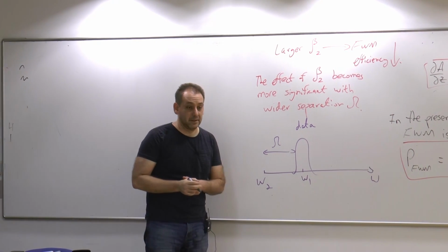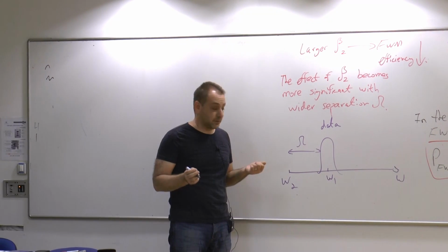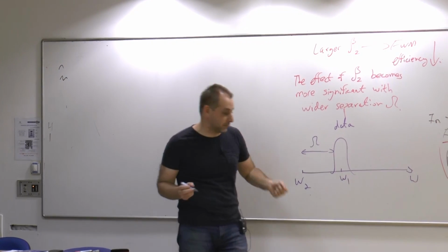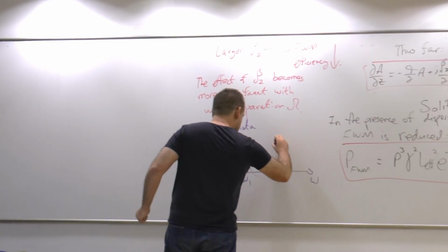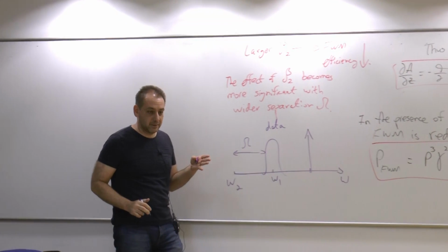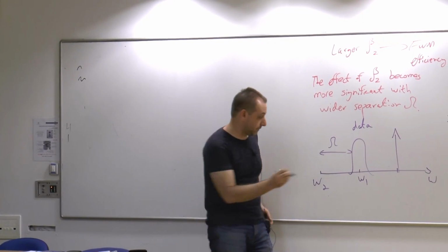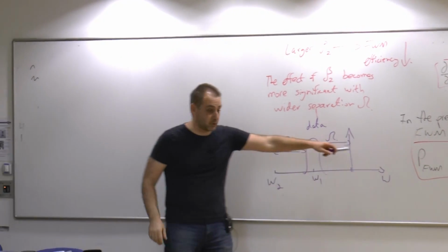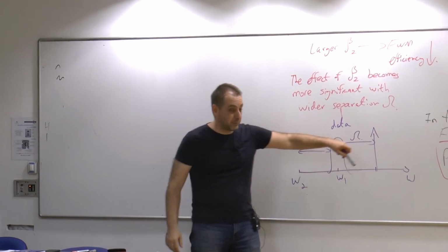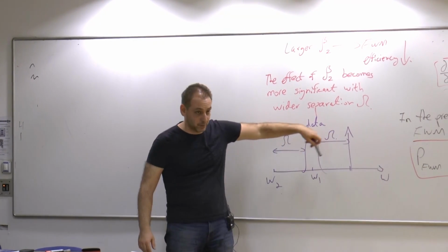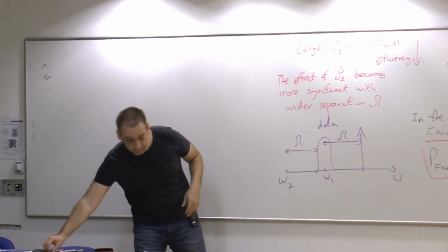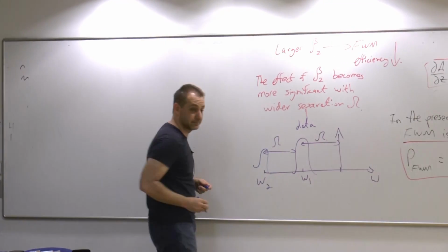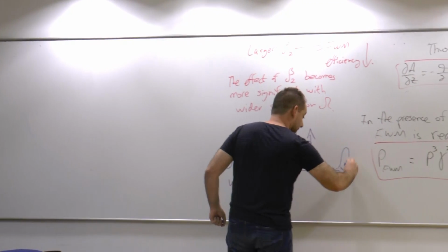difference to the right. Well, one thing you can do is add another dummy waveform, even a continuous one, with no data or nothing, but just intense enough to the other side. And if this is strong enough and that guy is strong enough, four-wave mixing is now initiating between these two, and their product is landing out here. Actually, and out here as well.